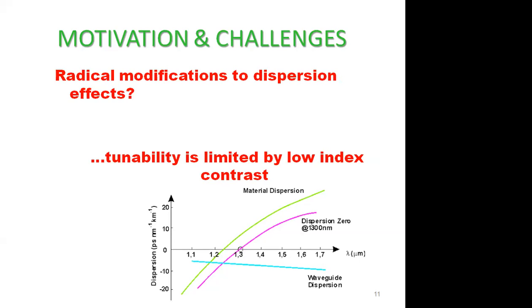Now drawback is what? Is it possible to shift from 1.3 to 1.2, 1.1? That is not possible in single mode fiber, because there are some applications wherein 800, 900 nanometer window is also used. At that point, we have a minus dispersion. And in case of single mode fiber, it is not possible to shift below 1.3. Above 1.3, you can shift anywhere. So what are the two drawbacks? Core area and then the dispersion. So these are the two important motivations for going to what? Which topic we are discussing? Photonics.